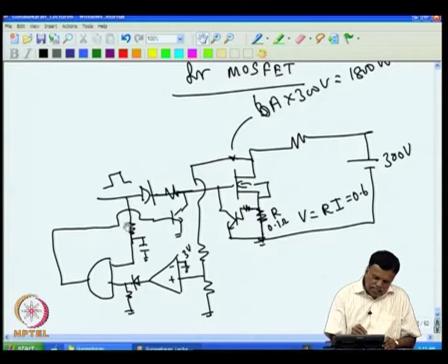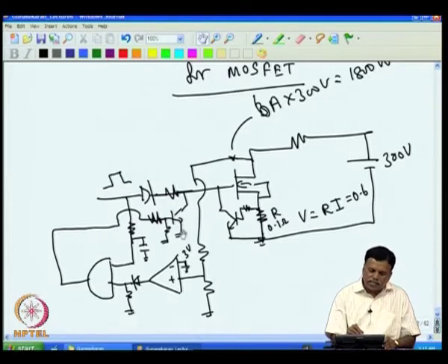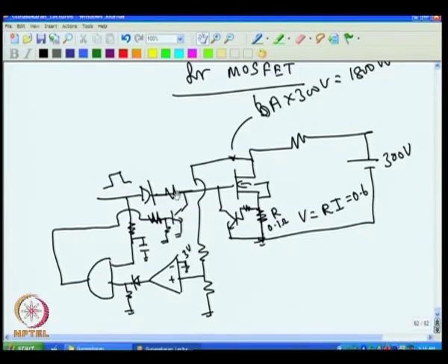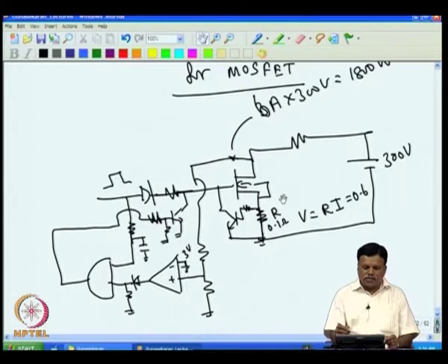Now, since this is high, this is also already high, and this will go here. Sorry, I had to add that resistance here to protect the base. So, once this output goes high, this transistor will conduct, and that will make this go to 0, and the MOSFET will go off. Once it goes off, there is no problem, this is still high, and this is still high, and we know that this command is also there, it will be high, and it will be completely latched.